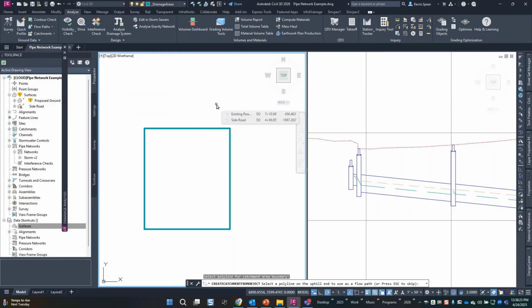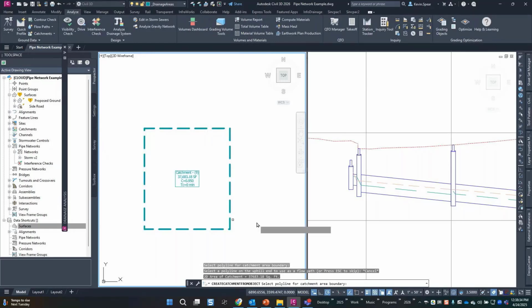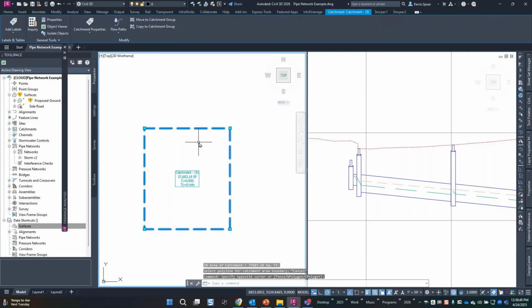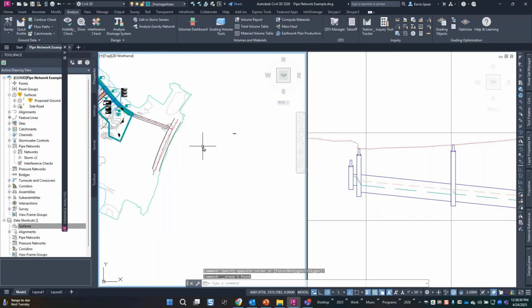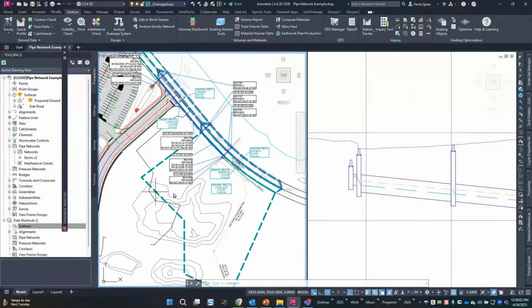It's actually asking for the flow path right out of the gate. So I typically just hit escape to do it later. And then it's happy to move along and do its thing. So that's the only caveat that some people get hung up on. They end up picking the catchment boundary as the time of concentration too, and that can get a little wonky in some of the calculations. Cool. Did that answer the question, I guess, to some degree? Okay.